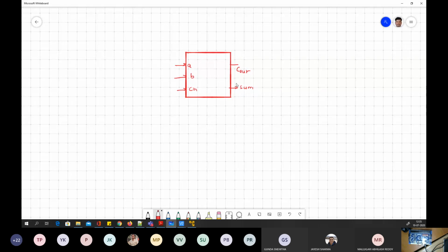Of course, everything is happening in the software, though there are switches inside the FPGA which get programmed so that the respective connections are made. So your intended connections you need to mention in your XDC file, and the rest of the job the tool will do for you. It's a way of specifying your intention: which signal needs to be connected to which switch, or which output should be connected to which LED. Okay, am I clear?